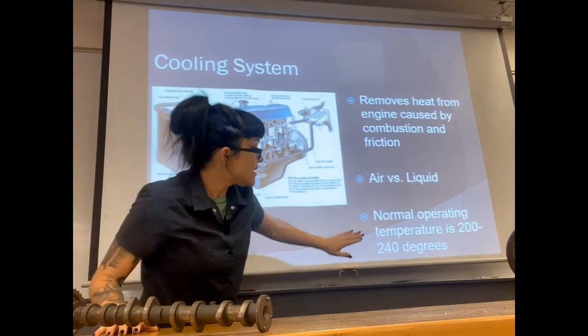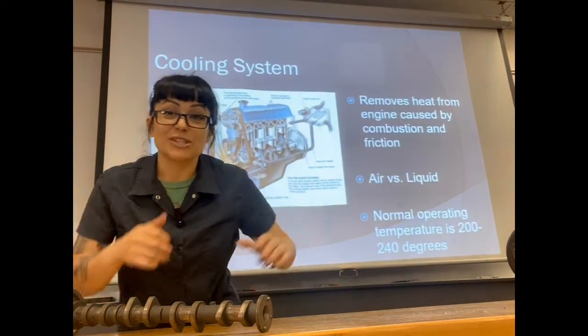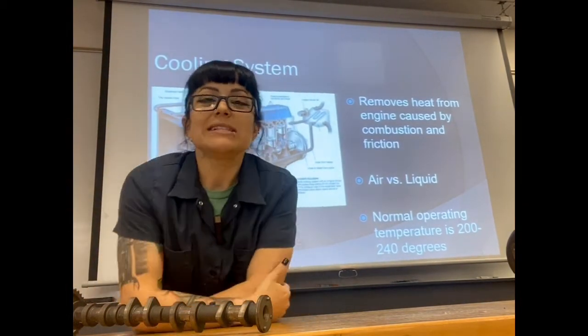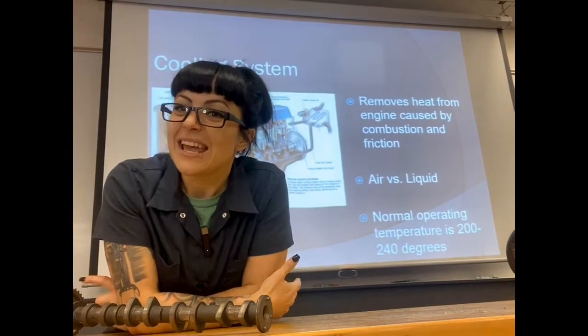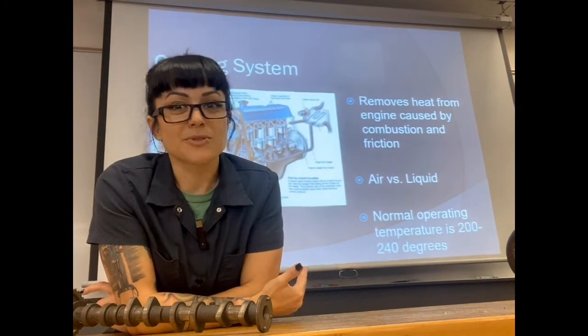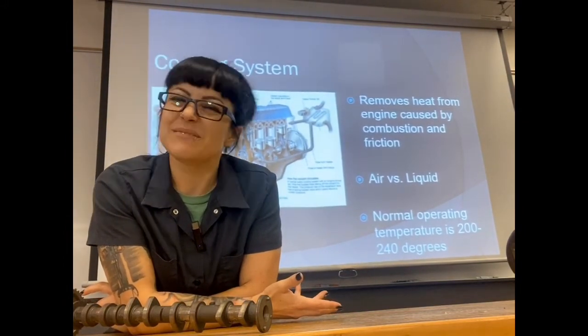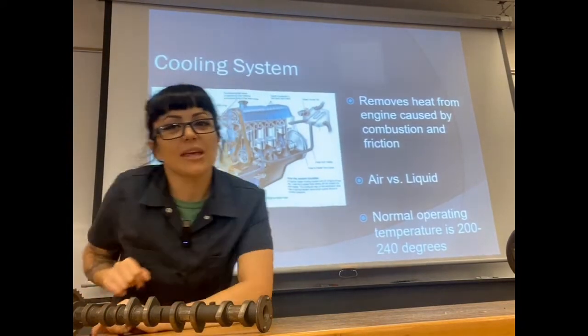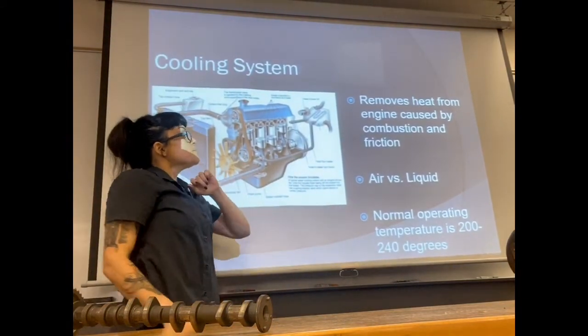Now, when we start to exceed that 240 degrees and keep going up, that's when we run into issues like overheating, and then the overheating will run into other problems like blown head gaskets, warped heads, and bad stuff like that. So we'll get into that when we get into cooling systems.